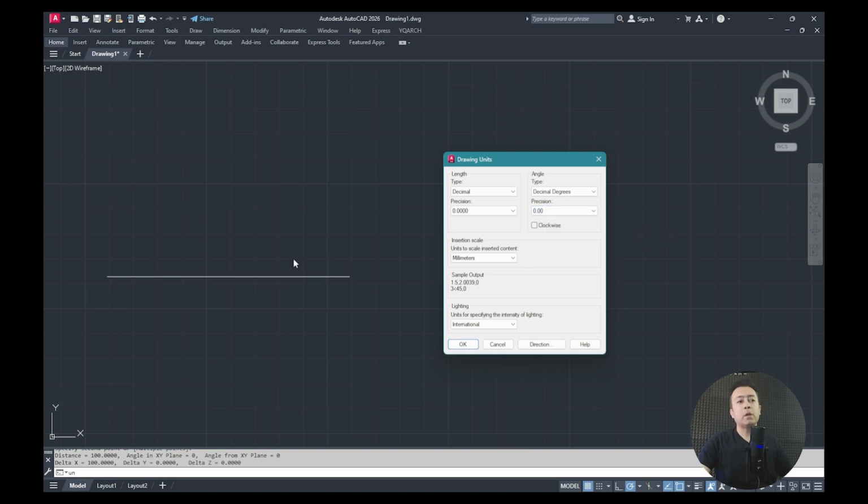In this way, by default, AutoCAD takes this X direction as 0 degrees and starts from here and rotates until it reaches 360 degrees. But you can do this in reverse. You can check the clockwise box here. If you set it to clockwise, this will be the opposite, meaning it will rotate clockwise from here. It rotates this way, 90 this way, 180 this way, 270 this way. Well, it's not very common. Why do I have to do anything else? Because according to the standard, angles always rotate this way. In fact, they rotate counterclockwise.